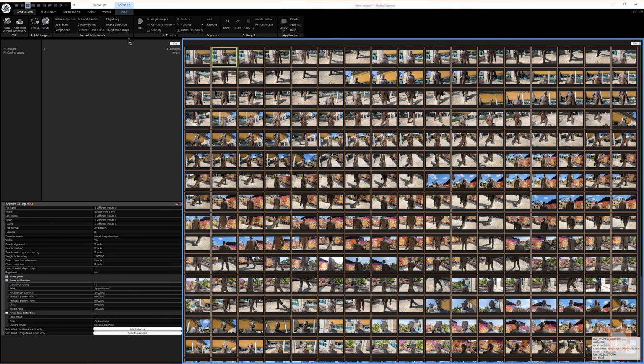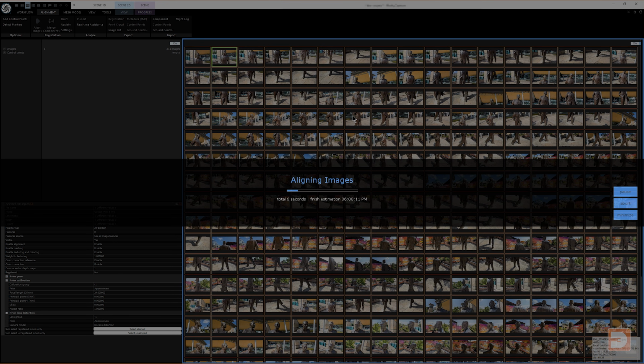The exact steps to follow when processing images for photogrammetry vary depending on the software you're using, but most of them follow a fairly similar path. Import all of your images and get them aligned. The software may flag that some of the images have been omitted and it can't find enough comparison points in it, but as long as this is kept to a minimum, that should be fine. This alignment might take a while and will depend on the complexity of the scan and the power of the computer, but can take anything from a few minutes to several hours, even with a powerful computer.